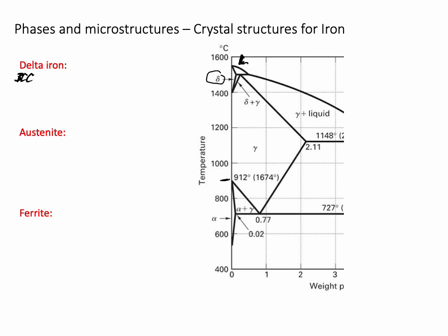That is called austenite, and austenite is FCC. And note that austenite can hold up to 2.11 weight percent carbon. Weight percent carbon is our x-axis. So FCC iron, gamma iron, or austenite can dissolve up to 2.11 weight percent carbon. And of course that is as an interstitial defect.